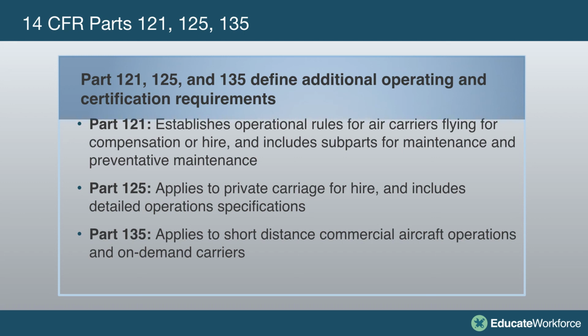It's going to identify special airworthiness requirements, which deals with many of the mechanic aspects of a passenger or cargo aircraft. And then subpart L is maintenance, preventative maintenance, and alterations. It requires that a Part 121 operator must have an operations manual which contains the following information. It's going to have an organizational chart, a list of personnel who may perform required inspections, company maintenance and preventative maintenance alterations, and a system to both preserve and retrieve maintenance inspection related information.